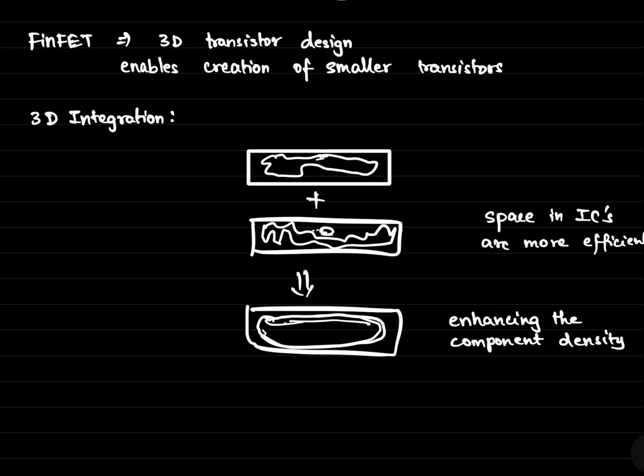Due to mechanical stress or temperature differences and a lot of these external, environmental factors, the soldering which connects the wires and the components together can degrade, it can get weakened over time, and this will cause the malfunctioning of the ICs. But by eliminating these solder joints, the malfunctioning of ICs due to mechanical failures can be reduced.